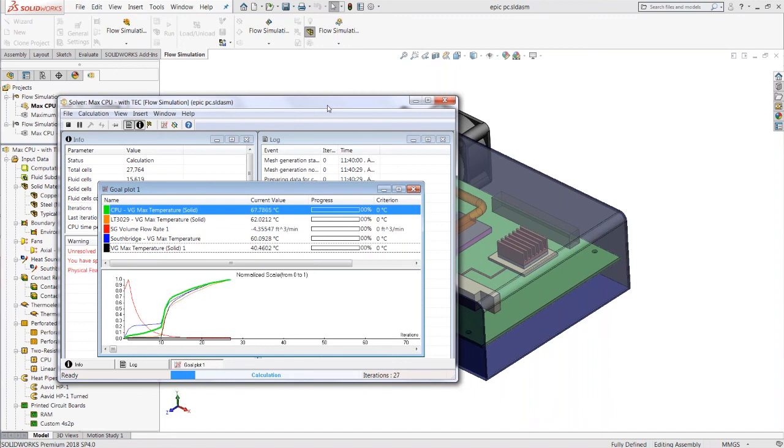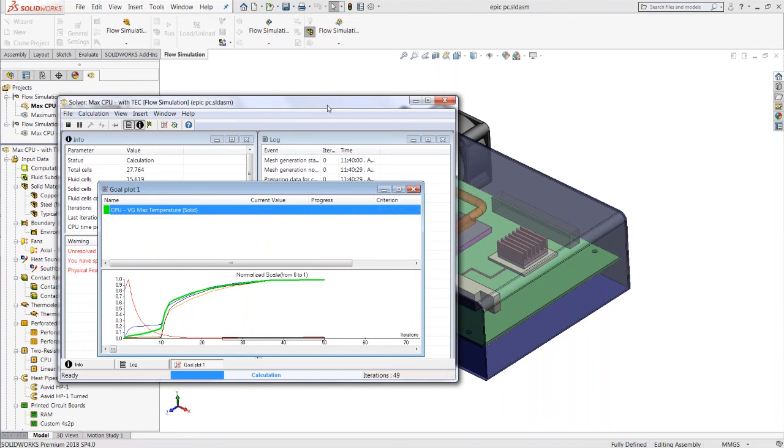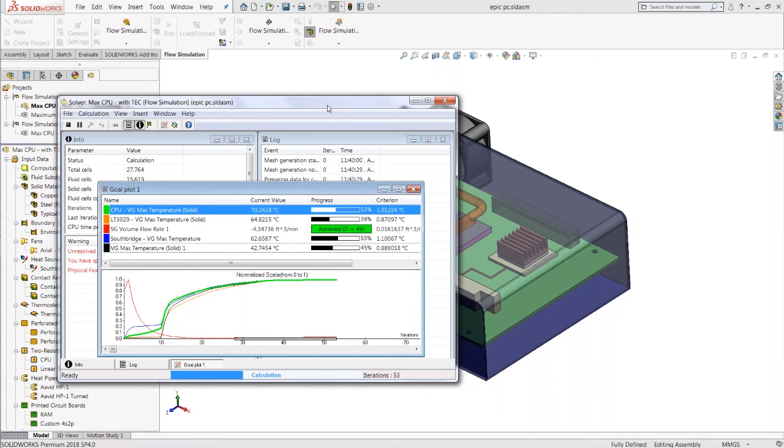And the simulation is essentially going to keep looping those airflow patterns until it hits what we call convergence. And what convergence means is just that we've found the steady state behavior of this product. The airflow patterns are all constant, the temperatures are no longer changing, and this is going to mimic running the device for a long period of time until everything stabilizes. And so once you start to see all of those little charts in the solver window level off, you'll know that we're getting close to that convergence. And of course, when it happens, all those little progress bars will light up green and the solver will finish.